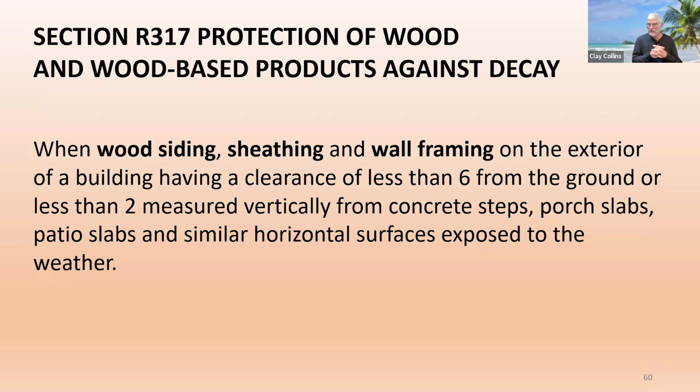We use that 6 inches from organic materials, 4 inches from masonry to soil. That applies to the stucco as well, and then 2 inches. So your stucco should be at least 2 inches above the concrete steps, slabs, patio slabs.